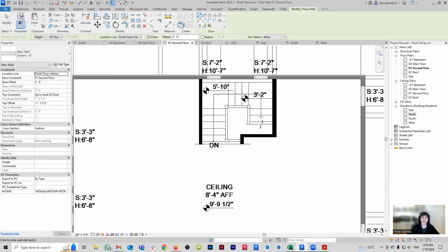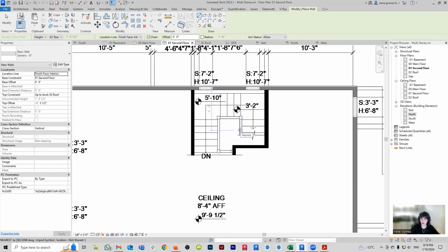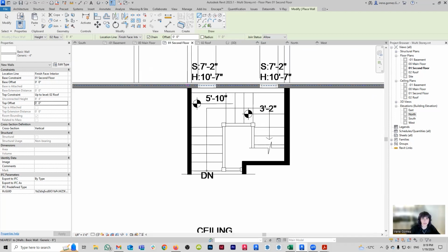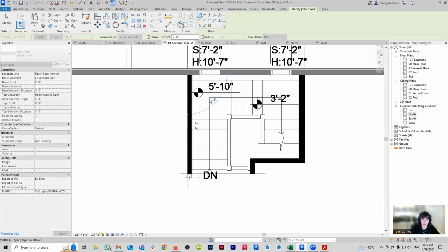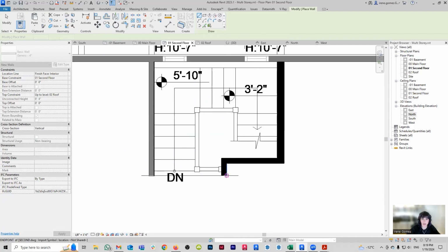Okay, so here just a little quick note for the walls in the second floor. It has to be a 4-inch wall, and the one thing that I want to point out is that this is going to be a case where we no longer need that offset, because remember, the top of my room is no longer a floor, but a roof, and roofs are always extruded away from the level. So I no longer need to do any math. Incredible. So just remove that restriction, and then you're just going to create your walls.